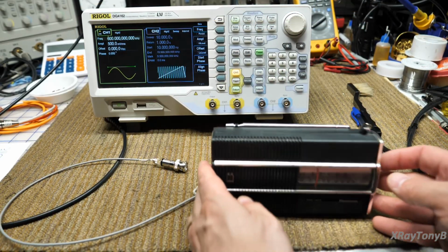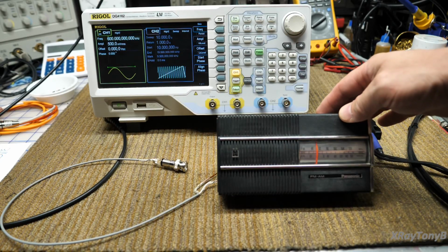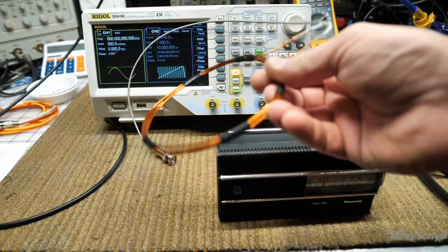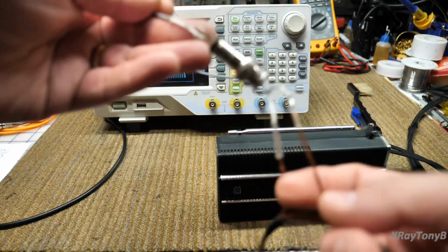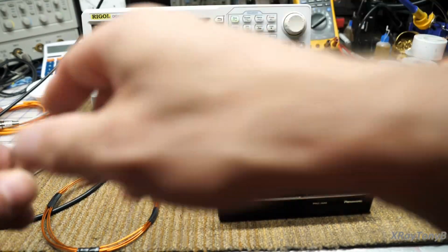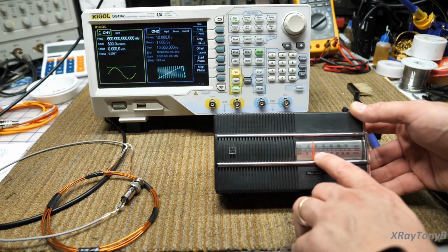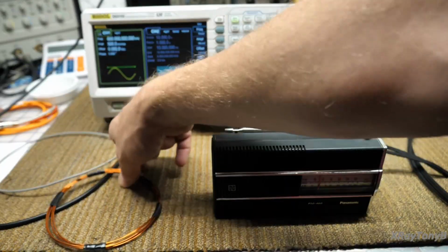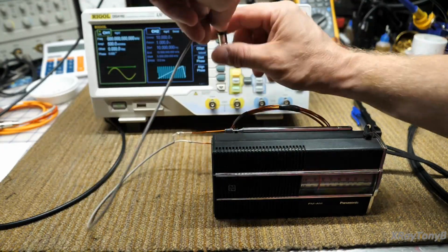Okay, I have a radio here. It's just a little Panasonic, and you can hear there's static on it right now. Hear the static? And I just have a couple of turns of wire here, just some random turns, connected to a lead with a BNC plug on the end of it. And I have this set to the 600 kilohertz at 500 millivolts output. And I have this tuned to 600 kilohertz. Now watch what happens when I plug this in. I'm going to hold this close to the radio, and I'm going to plug this in.